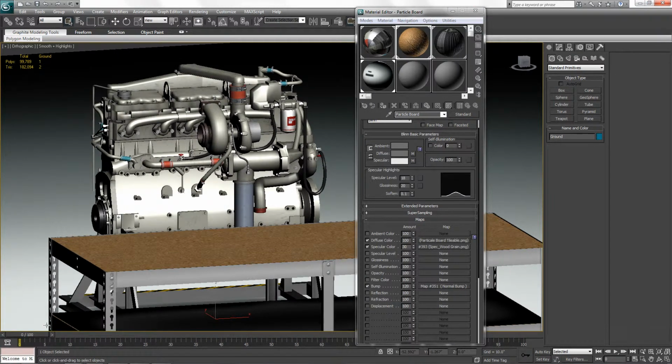And the third way that we can adjust the opacity is after we've created all the assets, we'll have these within the Replicate editor, and you can adjust the alpha values within the editor at that point on an object level basis. So how you choose to implement opacity is pretty open-ended. Generally, here at DISTI, we'll leave the opacity level alone within 3D Studio Max and control it in some other manner.